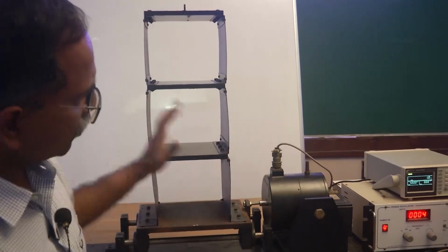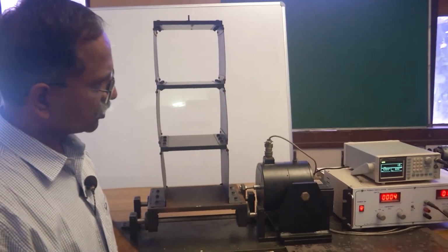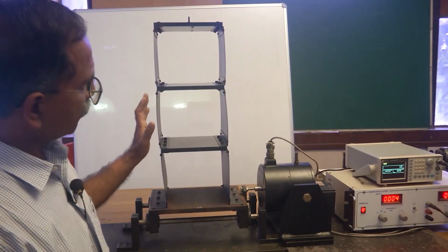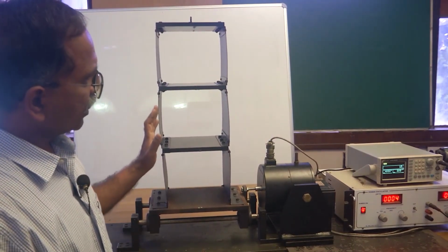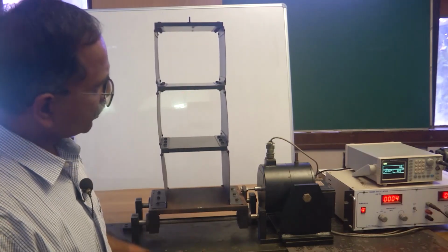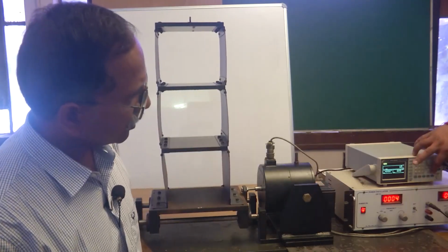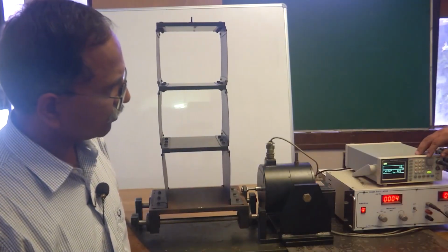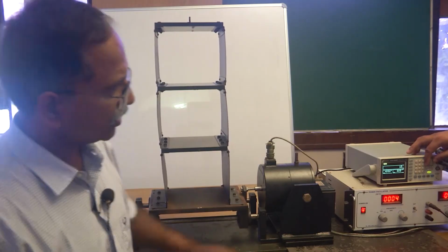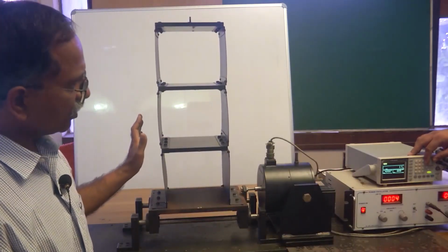So, we are going to now start scanning past the frequency starting from 1 Hertz onwards in the step of 0.1 Hertz, and look at where we observe the resonances, and at that resonance condition we are going to observe the way this multi-degree of freedom system vibrates. So Anuj is going to help us manipulate the frequencies in steps. So right now the frequency is 1 hertz, right, and this is the frequency 1.1 hertz now.